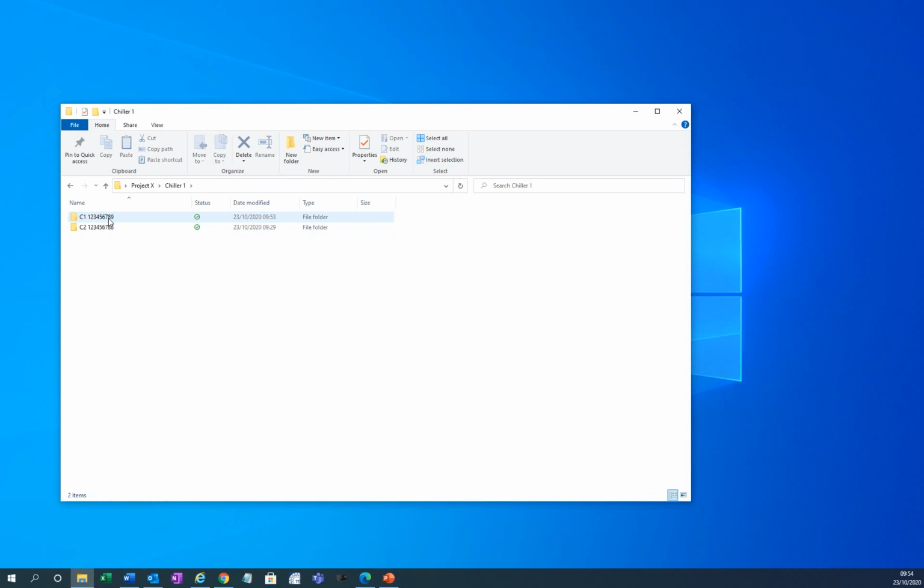And inside each chiller, I listed my compressors with its serial number. Remember that the serial number is a very important information that you need to provide in case you contact Danfoss Turbocor, because it's the only data that is physically printed on the compressor itself.